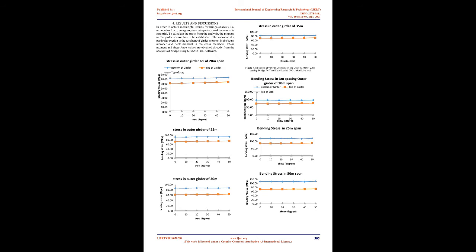Also, when we plot a graph, say, max bending moment value for each skew angle versus skew angle value, it would reflect smooth variation. The paper provides a detailed study of normal and skewed reinforced cement concrete bridges, various loading criteria on bridges as per Indian Road Congress, IRC 6, and amendments made recently, and different parameters like bending moment, twisting moment, and shear force under different skew angles from 0° to 60° at an interval of 5°.